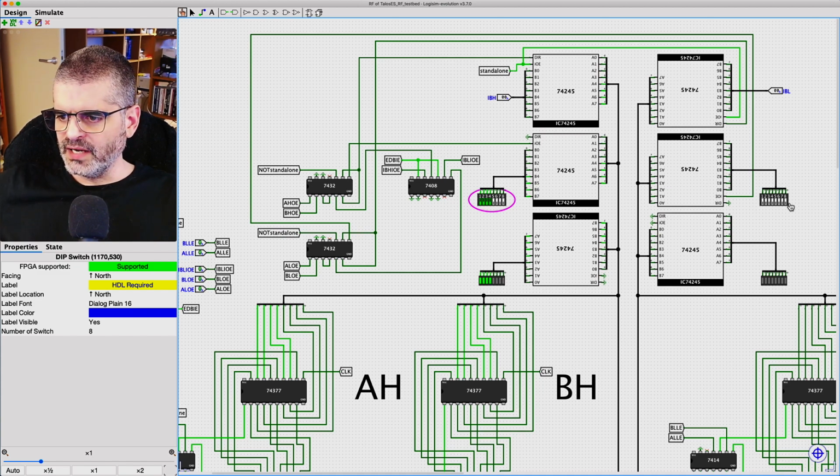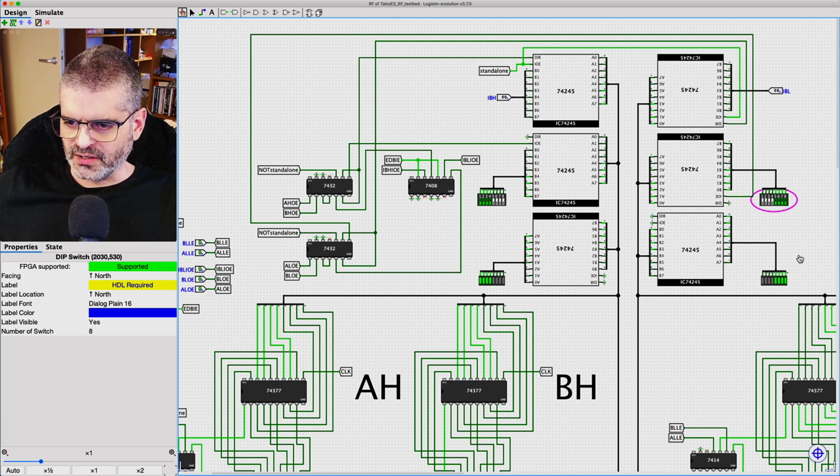And for the low byte, we switch on the low nibble, so we know which value is in what part of the bus. And you immediately see on the LEDs, because these two buffers are always enabled, they are always driving the LEDs, whatever is on the buses. So now we have a high nibble on the high bus and a low nibble on the low bus.